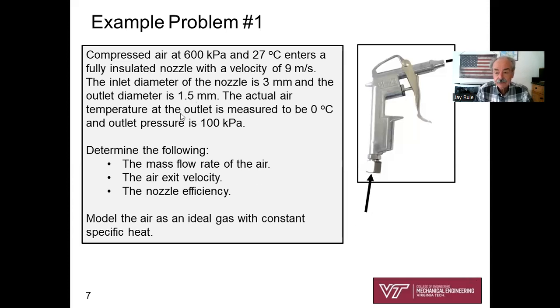The actual air temperature at the outlet of the nozzle, we've put a thermocouple in here and measured it to be 0 degrees C. Pretty cold, 0 degrees C, cold air. And the outlet pressure is 100 kPa. In other words, about atmospheric pressure.